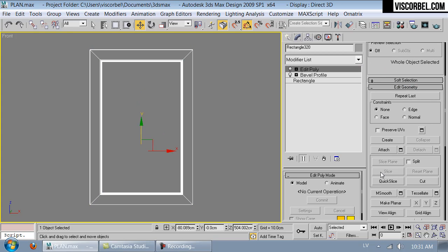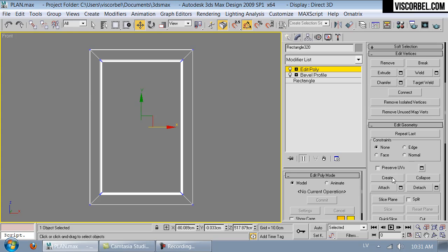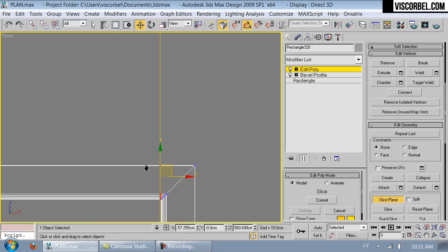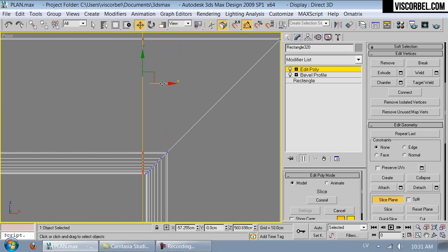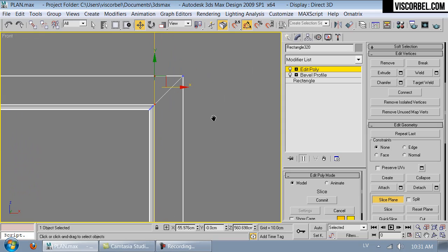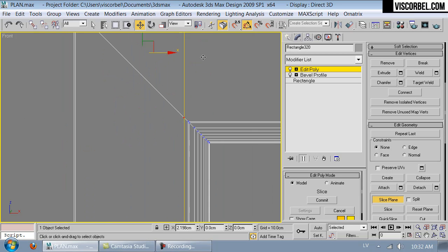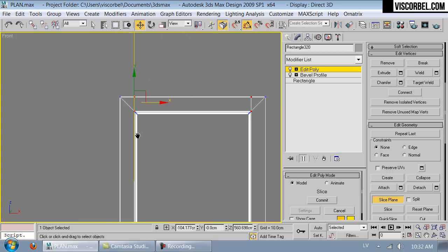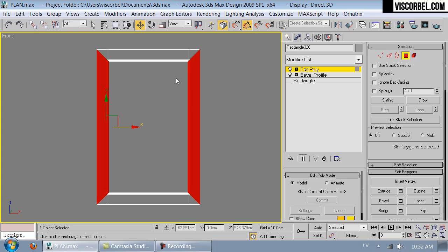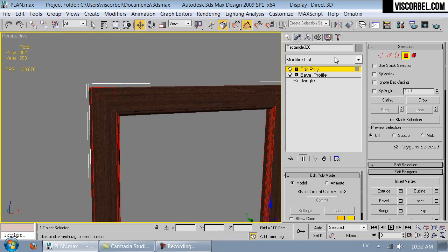Let's cut in the vertical seams like we did for the lower door, and basically position them in the same place. Okay, it doesn't need to be perfect. And these parts should have vertical grain, and the horizontal ones should have horizontal grain.